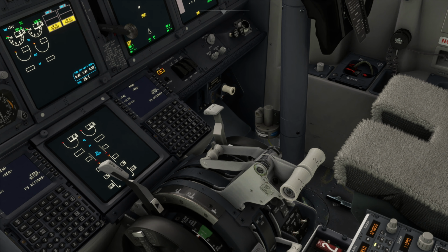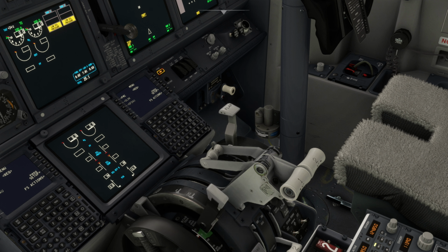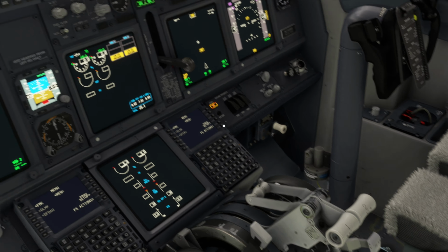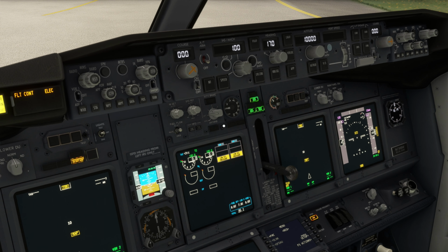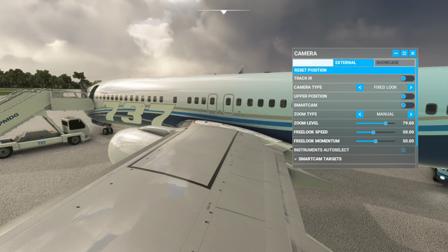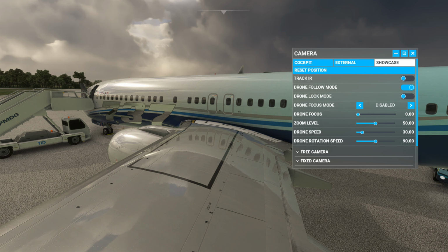Without any hydraulic pressure on the airplane, though, I can deploy our spoilers, flight and ground spoilers, as well as deploy our flaps down to 40 degrees, which is their maximum extension here on the 738. We have leading edge slats, which are protrusions that come out from the leading edges of the wings, as well as the trailing edge flaps, which will extend from the trailing edges of the wings. Nothing is happening here on the wing surface because we have no hydraulic pressure. These are hydraulically actuated surfaces.